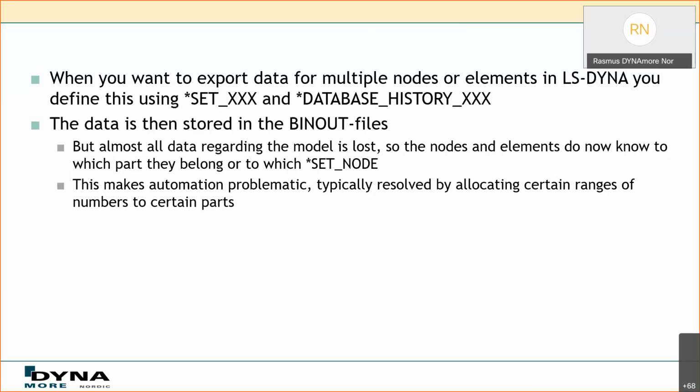What can typically be done is, for example, resolving ranges of node IDs, or element IDs, for a specific task. But this, of course, hinders the modularity a bit. You have to kind of hard code it into the post-processing, and you probably can't use it for the next simulation, or if someone else is building the model, you have to tell them exactly how you're going to build it and such. So it's, yeah, it's not optimal, so to say.